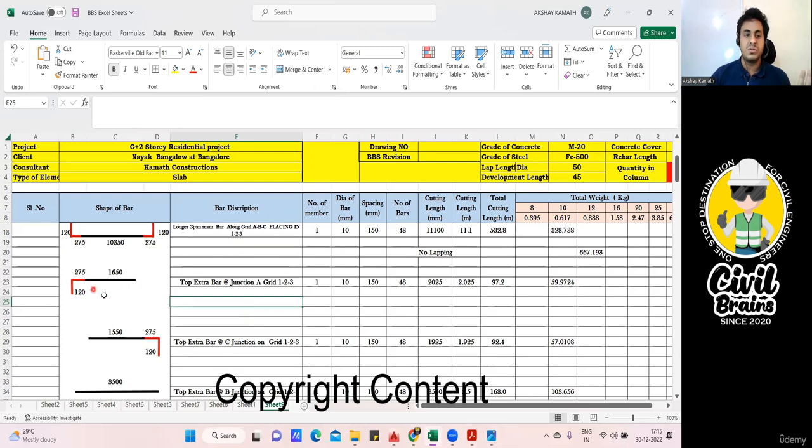Okay. Everything I have shown. Simple. This much is done. This shape I have drawn like this. Fine. Now I write the top extra bar at junction A, grid 1 to C. So again, the number of members is 1. Diameter is 10. Don't look at the diameter and spacing. For all the calculations in the slab in this project, it is 10 diameter bar at 150. So 10 and 150, you do it.